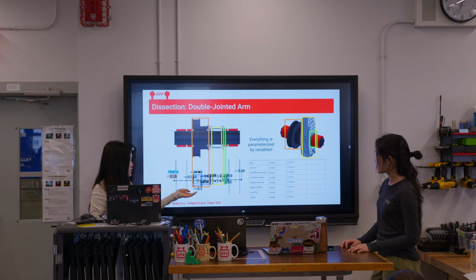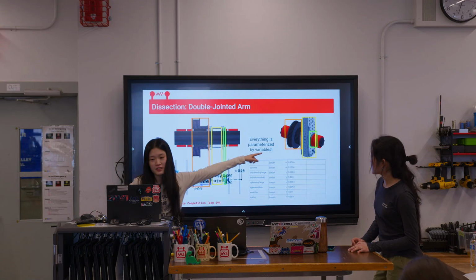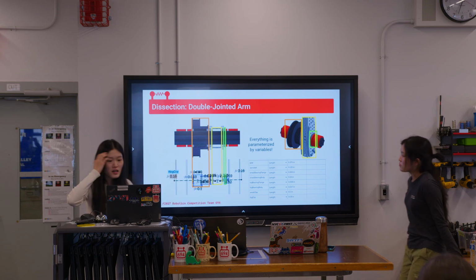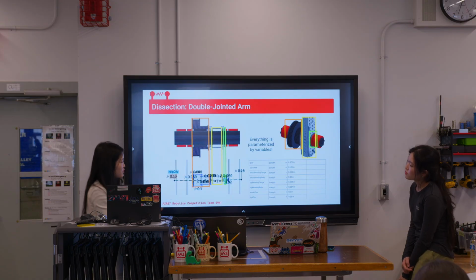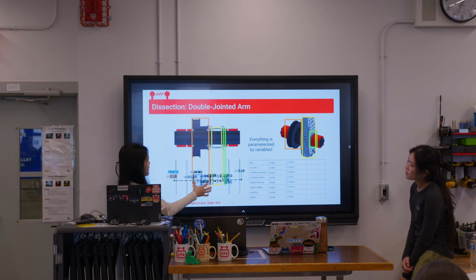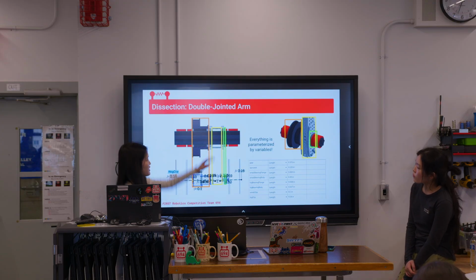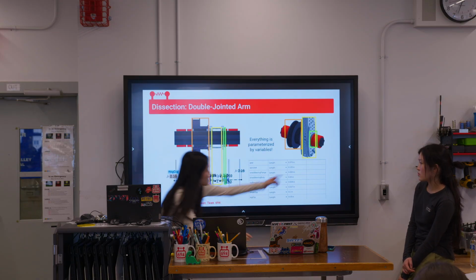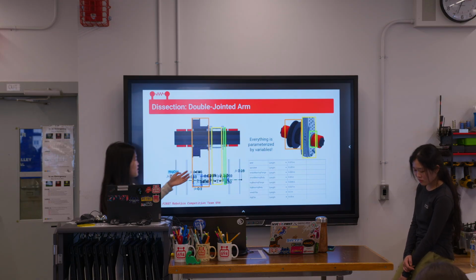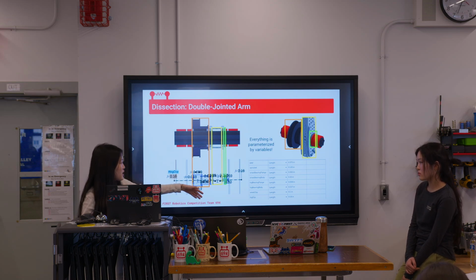This is the sketch for the first joint, and this is the assembly for the first joint, and this is just a side view of how the first joint looks, which is the first pivoting part. If you see, the sketch was done before, and then all these components were laid on top of it. This represents the pulley, so the pulley is here, and then this is a tubing. This tubing was also on here, so it perfectly lines up because it was made based on the sketch. I even have things like the bearing flange lined up here, sticking out of here. All of that is made on the axle sketch, from the top view, so when you make these parts, they'll always perfectly line up.